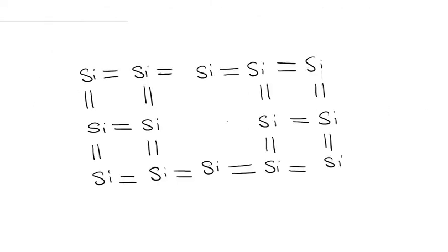Now this diagram again shows bonded silicon atoms, and one boron atom is, let us assume, sitting in between them here. Boron only has 3 electrons in its outermost shell, or 3 valence electrons. These 3 electrons form 3 bonds with the neighboring silicon atoms.